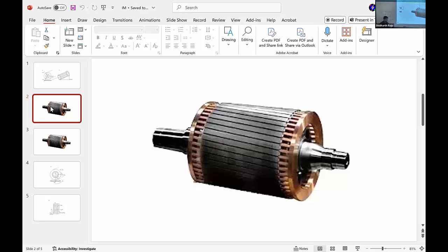Reluctance, perfect. So when you don't have that iron core, the magnetic field coming from the stator is going through a very large air gap, right? And when our air gap length becomes large, our equation was mu naught N S P divided by Lg times I times cos of theta for the magnetic field due to the A phase winding. That Lg factor becomes extremely large. So you want to make that Lg as small as possible.